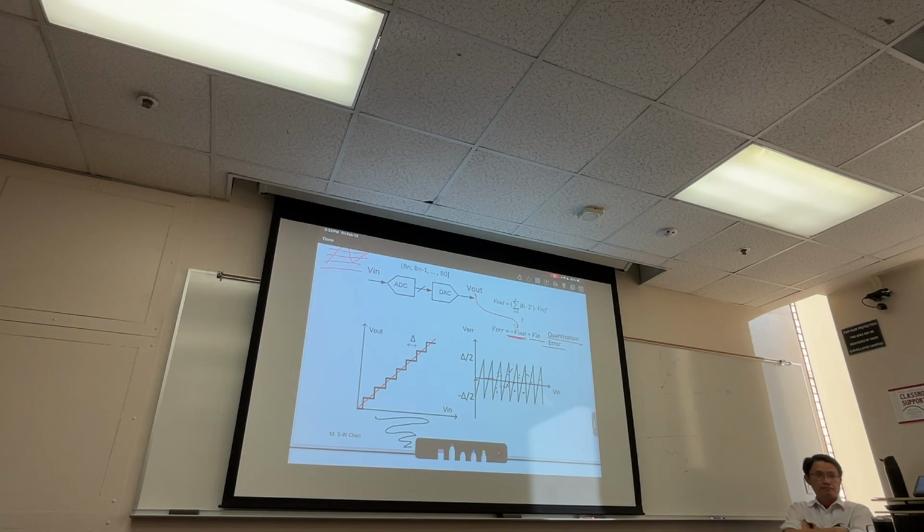Define from sample to sample. Sample just like an ADC, right? So you quantize in time and quantize in amplitude, right? So the first sample, that's the first delta function that you multiply with. So you take the first sample, second sample. If you need to visualize, if this is my input to the ADC, first sample, second sample, third sample, fourth sample. Are the V errors associated with those samples independent, or dependent, or correlated?